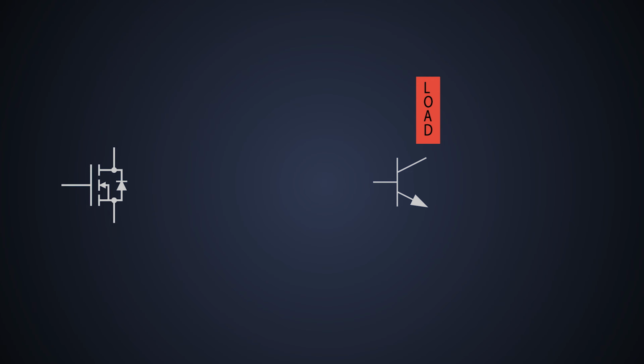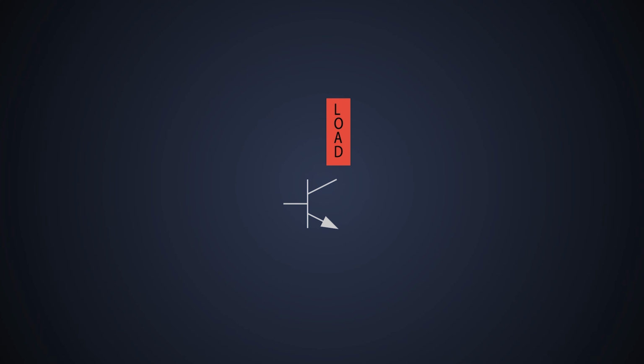You know what? A transistor can provide a regulated supply of current. We can use a BJT or MOSFET depending upon the current and voltage requirement. So we can add a load to the transistor. We can bias a BJT at its base and a MOSFET at its gate. For now, we'll consider a BJT.